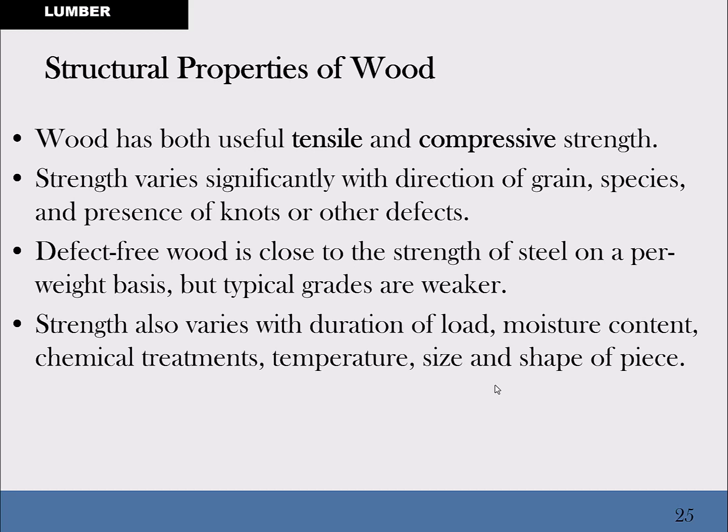And so pressure treating is a problem. It's a good thing when you're trying to fight the bugs, but generally, if you have to make a pressure-treated piece of lumber structural, where it's going to be supporting a load of some kind, like a beam, you need that lumber to have been either re-seasoned, where it's run through a kiln, or dried out over time, one way or the other. You don't want moist wood being used, even when it has a pressure treatment, because the bugs won't eat it, but it can still change shape and be a saggy old beam in the end.